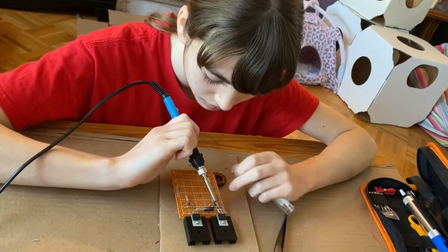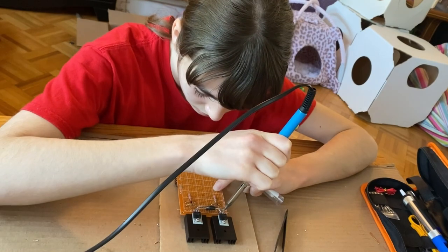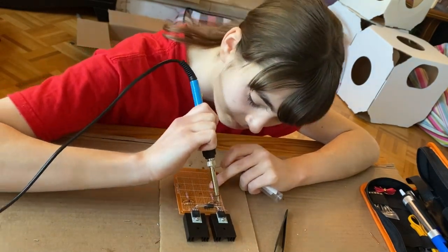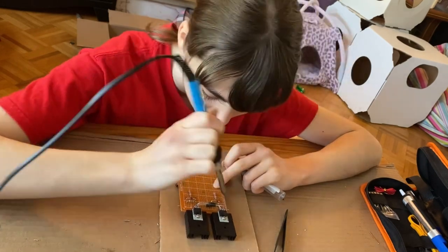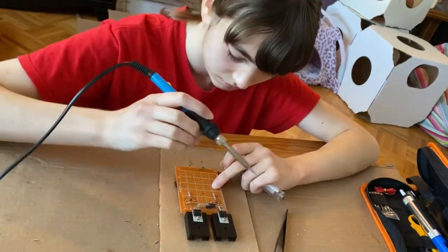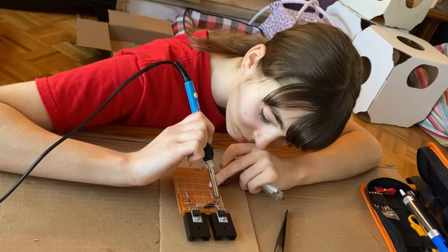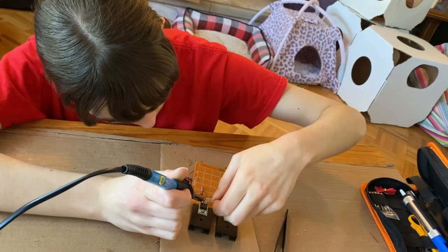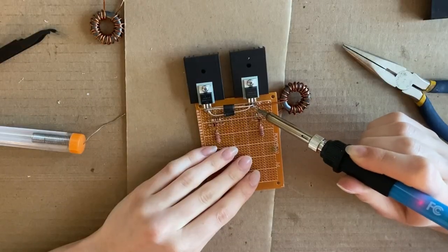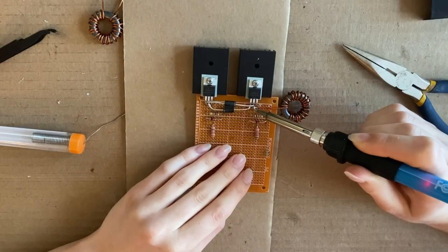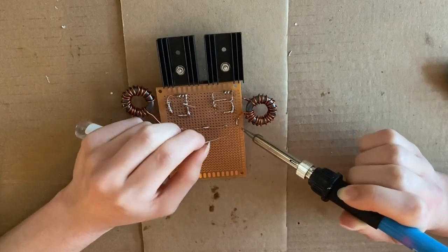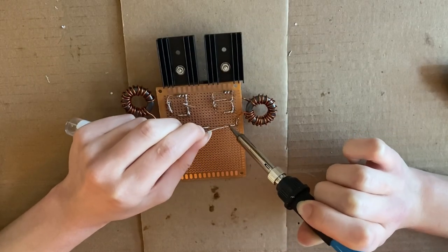suggestions to change it. These suggestions would be things like look for a capacitor with a higher AC voltage rating, which I would do by looking through DigiKey, which I ordered my components off of, by putting in the parameters I need, such as a specific voltage rating, as well as looking at the datasheets of the components to see what is best for my circuit, which would be the values I used on my LTSpice simulation, as well as what it can handle.